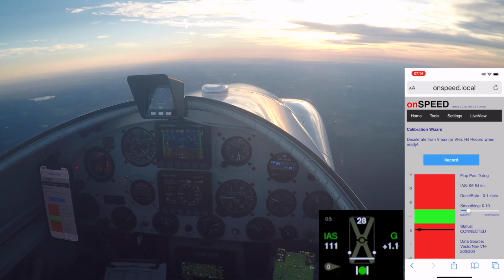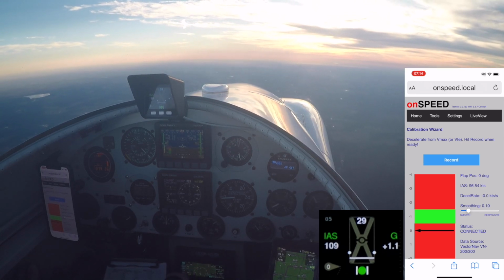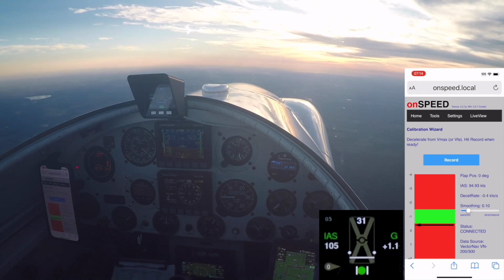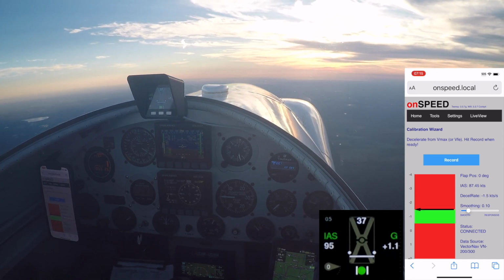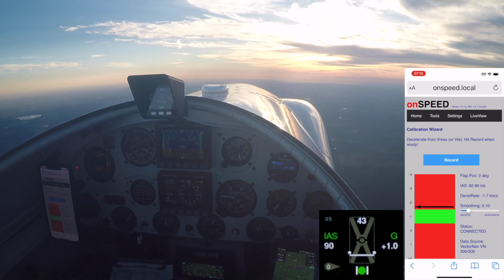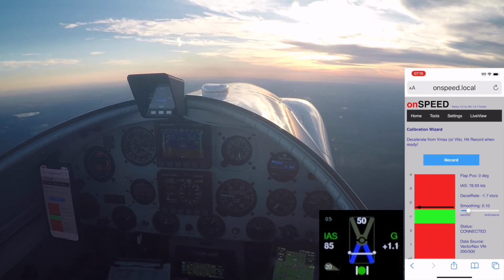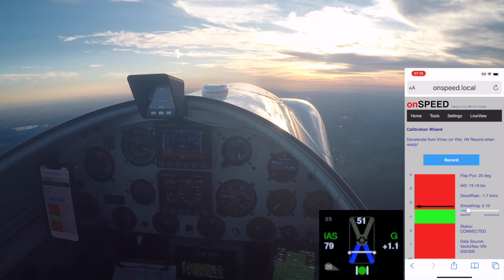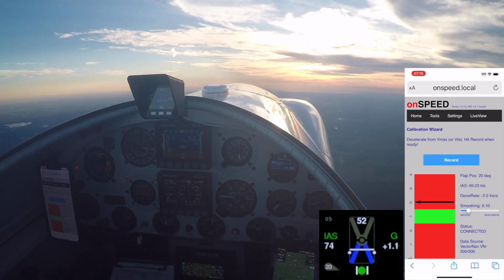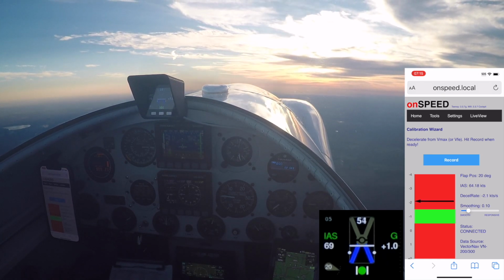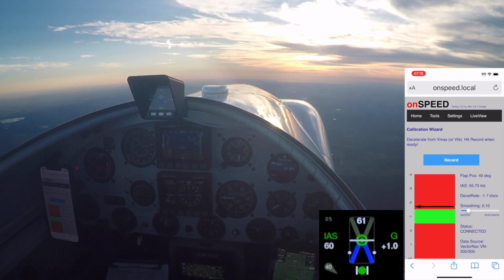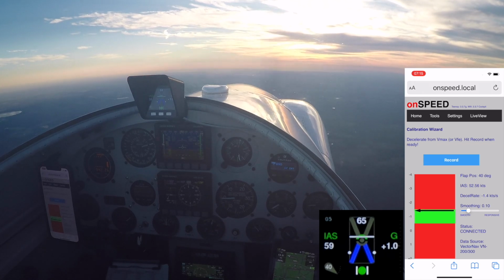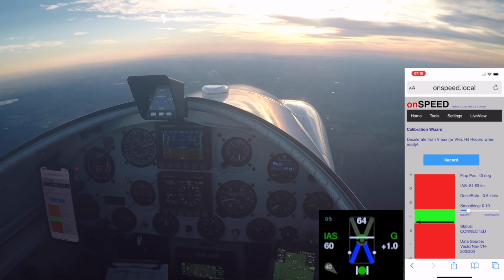The reason the flap indicator is in there is because obviously if we're testing angle of attack, we're going to want to know that the system is getting good feedback about the flap position and I'm on the proper calibration curve. So let me just demonstrate that to you. I've got manual flaps, so the flaps move really quickly. Notice that's a flaps 20 condition, and there's a flaps 40 condition. I've just got 3 flap settings in there. I'm in an on-speed condition flaps 40 now, and I get the feedback I need through my energy display.